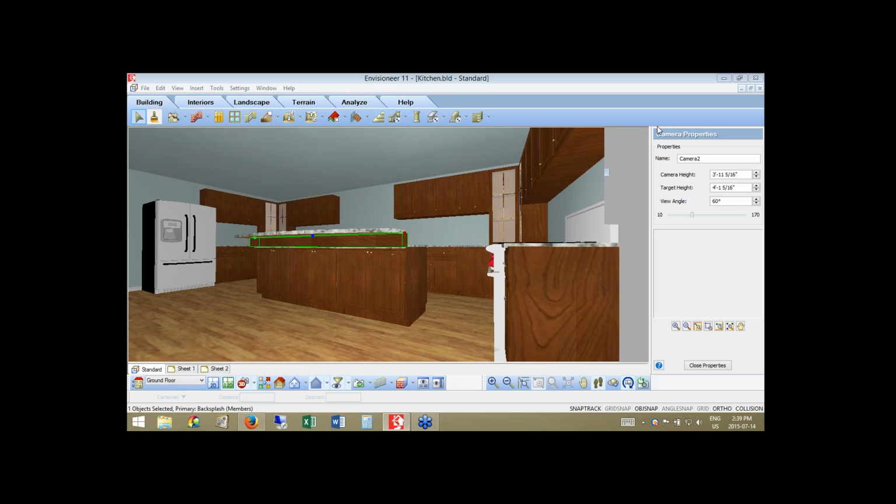If I'm going to zoom in here and go close here. Another way of putting it, like we put the countertop over the custom island, we could have eliminated this cabinet altogether and not had the gable ends on either side, just deleted it out. You can see it leaves a hole here, but using that surfaces tool, I can draw in a surface in that area itself. So it's not a cabinet, but just the countertop material going over top of it and our dishwasher sitting in there. So that's an alternative way, so you don't have to use an actual cabinet in that space.